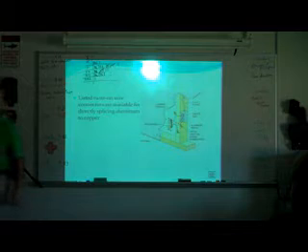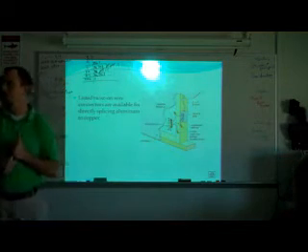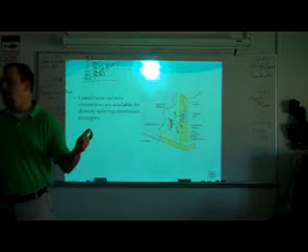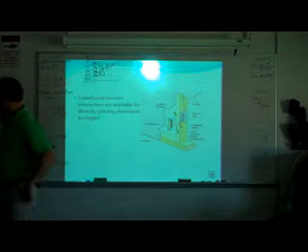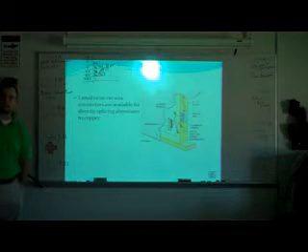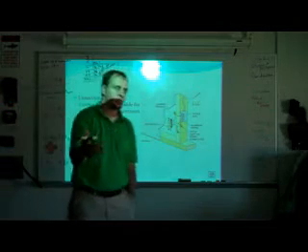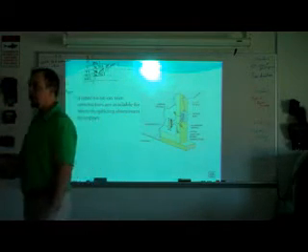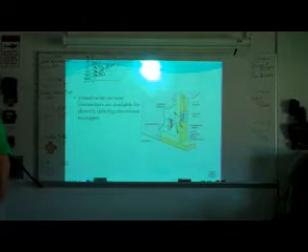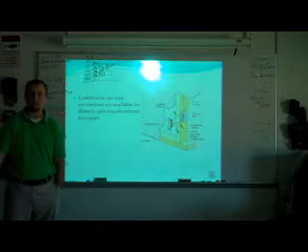Remember, I told you that my wires were rated for 70 amps. The most I was pulling was 50. I shouldn't have had a problem. But because of this loose connection, it generated more heat. Now more heat, added in with the current, shortened the life of my wire and overheated it, even though I should have been able to hold it. But it wasn't able to, due to that extra heat.